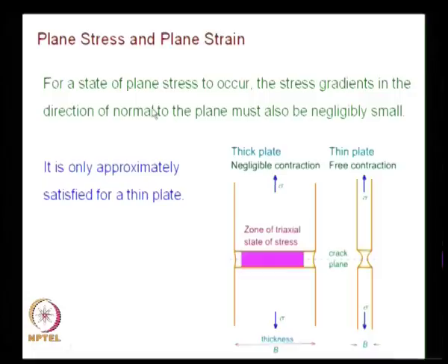So, you will have gradient of stresses developed in the thickness direction. So, in the context of fracture mechanics, though we say thin plates subject to in plane loading can be equated to a plane stress situation, from the definition of applied mechanics, the definition is strictly not correct. It is only approximately satisfied in a thin plate.